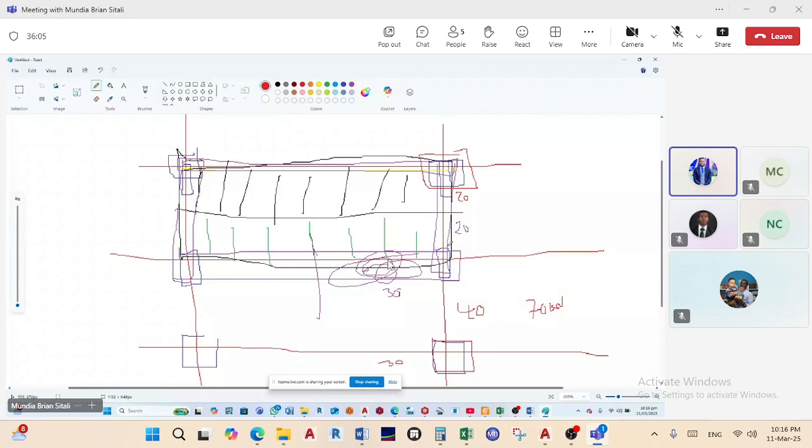That's why we say, okay, let's provide another grid, provide another column, and hide it in the same wall that the architect is saying has to be 200 here. So what we have done is that we have satisfied the requirements of the architect, but provided extra support for our structure.